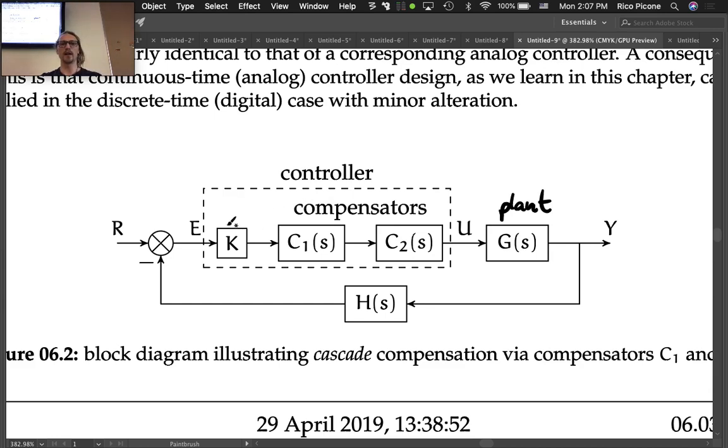So we've got the gain. What we do is we first design a gain controller using the same method from lecture 6.2, and that's our first controller design. It's the easy one. It's the one we know how to do already, just gain control. Adjust the gain based on the root locus, get as close as we can, and then the next step